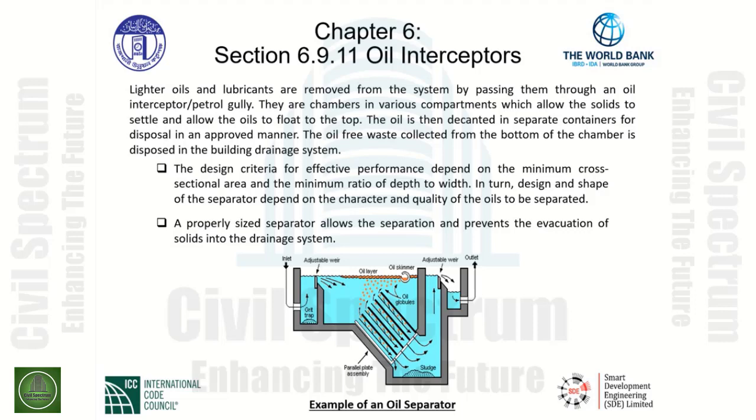We have the inlet entering the oil separator into a compartment that has an adjustable weir. This is the first area that will trap heavy particles such as dirt, sand, and allow that to fall downward into the compartment, allowing clean water to elevate and discharge above the adjustable weir. This also controls flow as well.